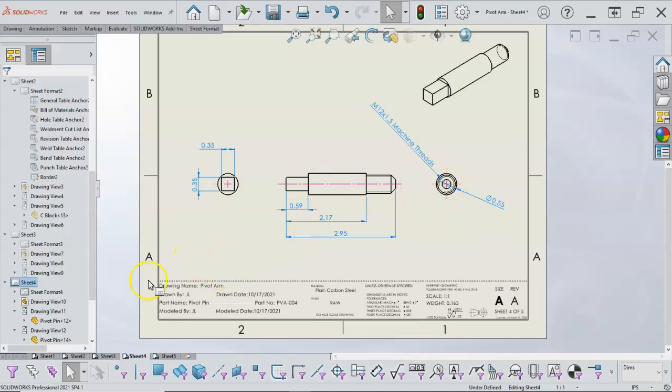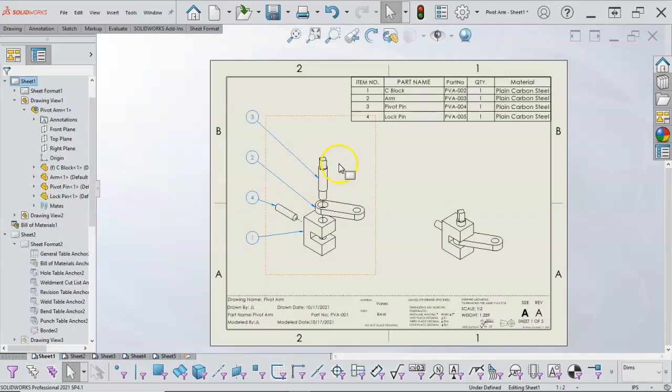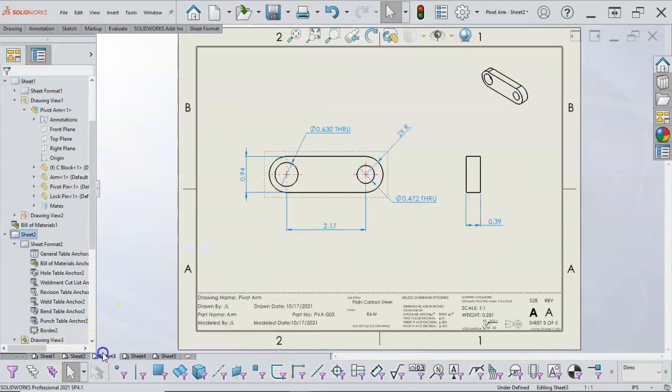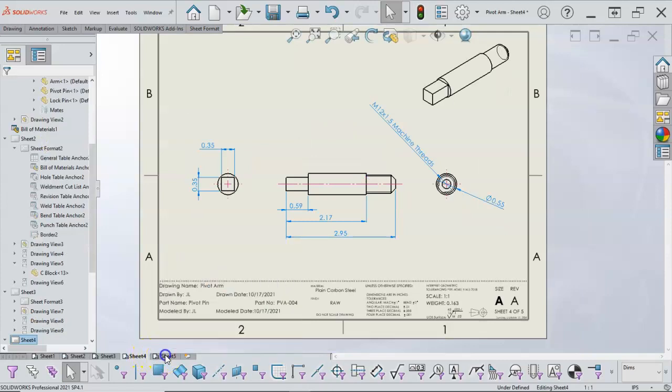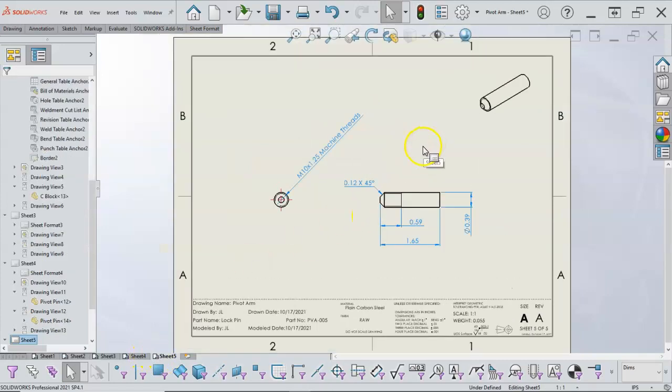But if we were looking at this pin being a tight fit, then we would want to look at adding a slight plus tolerance to a minus tolerance on the shaft, so that we end up with that clearance fit. There's not really too much here, and not knowing what it connects to or how it mounts, I think we have a pretty good drawing going, and we'll come back and analyze if we need to.